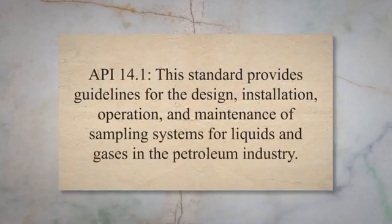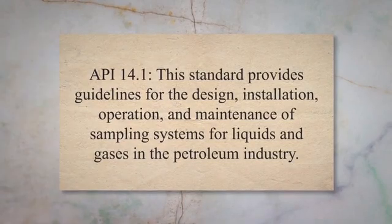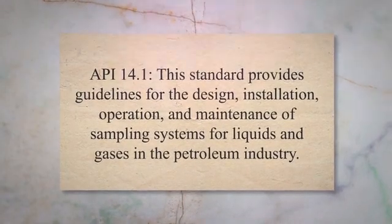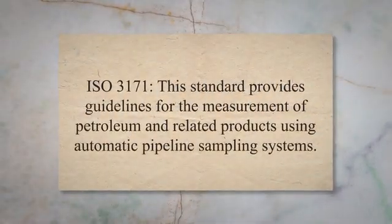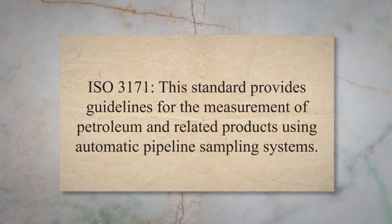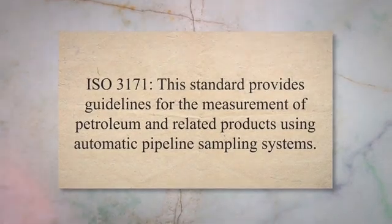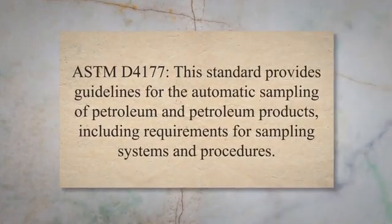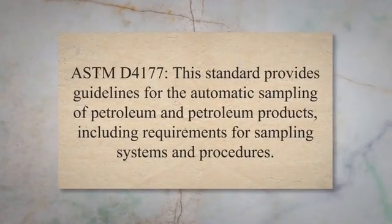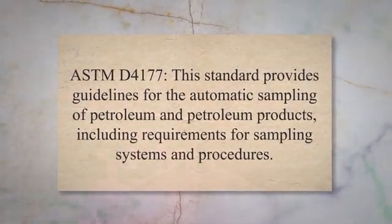API 14.1. This standard provides guidelines for the design, installation, operation, and maintenance of sampling systems for liquids and gases in the petroleum industry. ISO 3171. This standard provides guidelines for the measurement of petroleum and related products using automatic pipeline sampling systems. ASTM D4177. This standard provides guidelines for the automatic sampling of petroleum and petroleum products, including requirements for sampling systems and procedures.